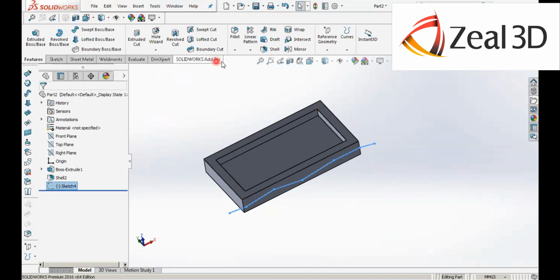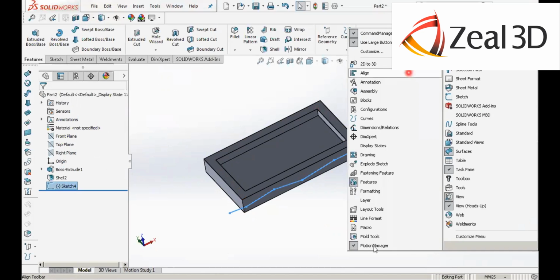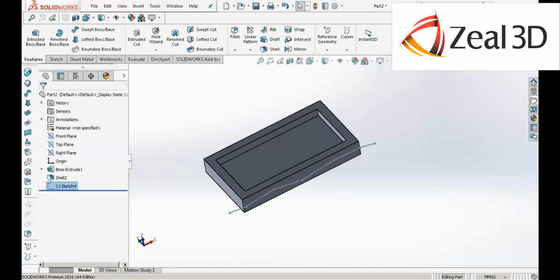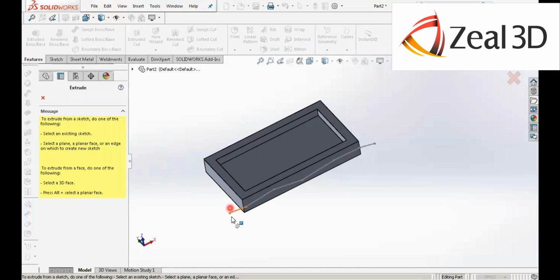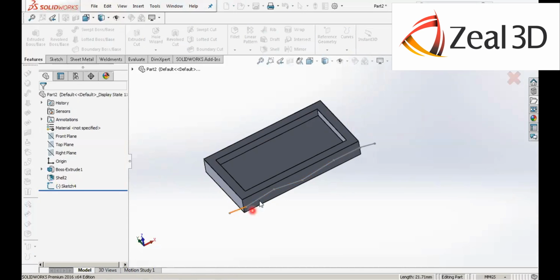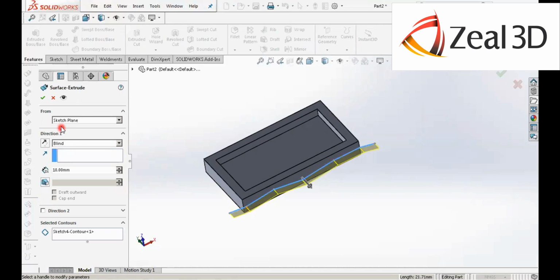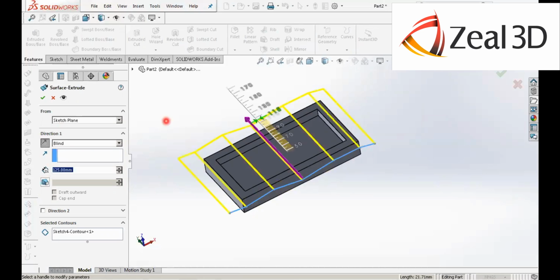And by that, we have also got certain advanced options, like the reduced angle, which allows only the parting line draft. When selecting this option, the draft angle on some portions of the draft faces may be smaller than the specified draft angle. And apart from it, we have also got a perpendicular step draft. So now we are looking at the next feature, which is the intersect feature.